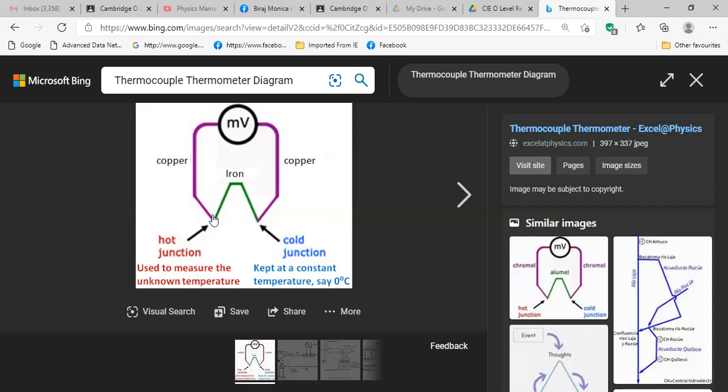So there might be, like, here is 1000 degrees Celsius and here is 0 degrees Celsius. This temperature change is making some EMF or electron flow through these wires, these copper wires, and the reading we are getting there is also linked with the temperature scale.